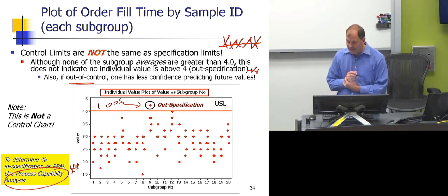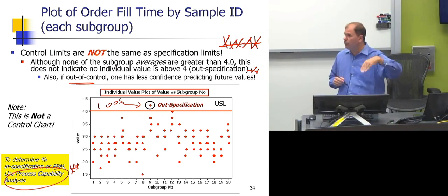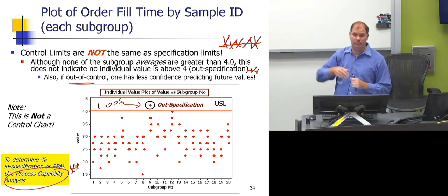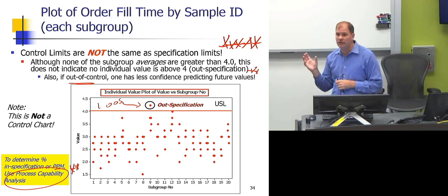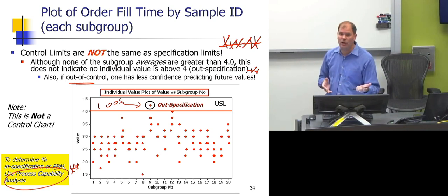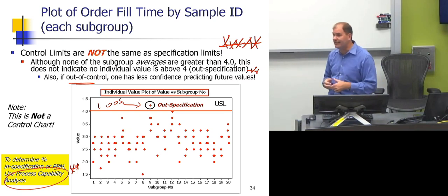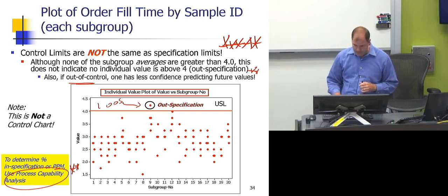And next time you do process capability analysis, you will notice that it wants the data in one of two formats, either a subgroup across a row, or it's going to ask you to put them in terms of a big column. And there's also what's called the 6-pack tool, which does both capability and an SPC chart in the same tool. I'll show that again in an upcoming lecture, but there's also a capability analysis 6-pack that does both SPC and the capability at the same time.